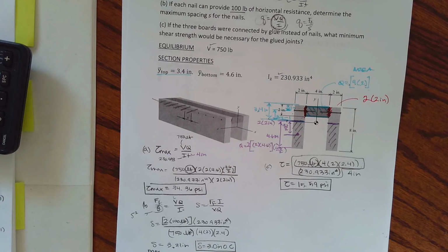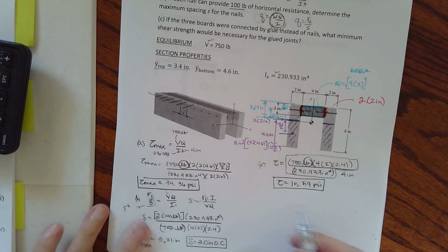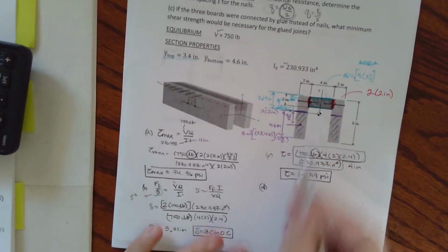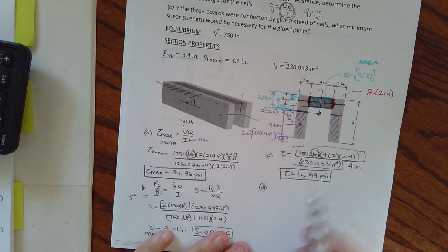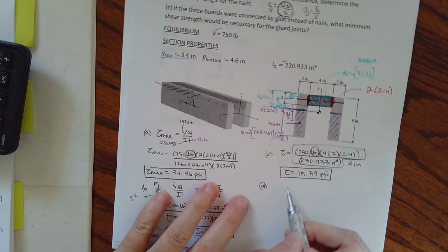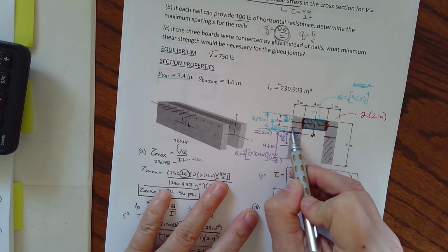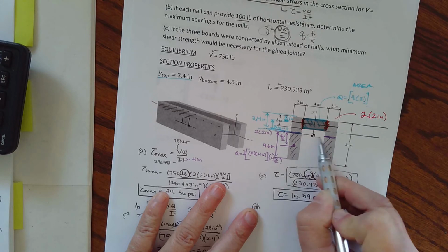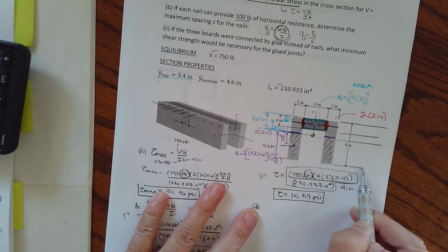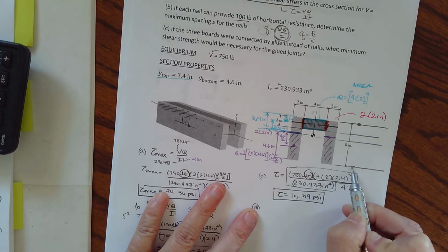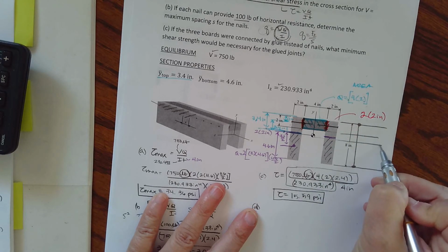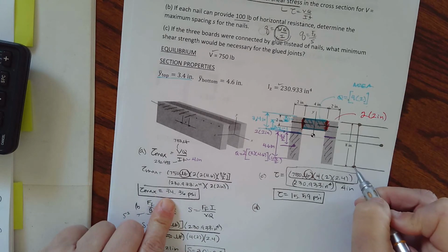Okay, so we didn't really talk about this, but we're going to figure out how to sketch this shear stress distribution. I know that it's parabolic with the maximum here. When I look at this, I have a transition in thicknesses, and I'm going to end up with kind of a bump. The shear stress distribution is 0 at the tops and bottoms, because we don't have any area beyond. I'm going to have a maximum here of 34.36.